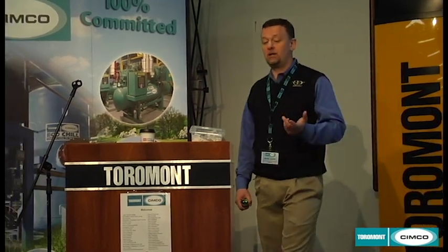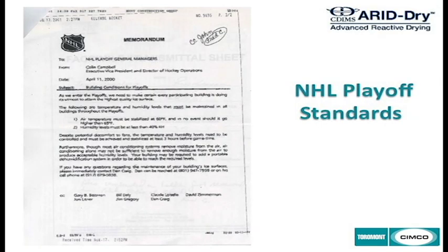Well, in practice, after years of employing this technology and working with it, we discovered that about a 35-degree dew point is good enough. You don't need to go quite that low. And the NHL actually has come to a standard that agrees with that. That letter that I just showed you, you couldn't read, so I'm moving on, was actually sent out to all NHL facilities in 2000 that were going to be in the playoffs. And they've set this standard, and I believe they're still following this for playoff mandated standards.